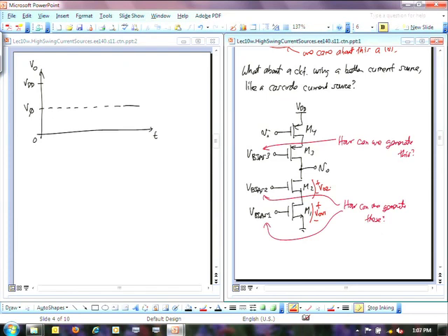And so because of that, I could say that V out min for this device is going to be 2 times an overdrive voltage. Right? And that would be the maximum swing that I can get out of this circuit here. That's what I want. Okay, so if I had to plot that maximum swing, then from the bottom, I might have 2 times an overdrive voltage. And from the top, now I've got 2 PMOS devices looking up that way. I've got to drop across this. The smallest voltage I could drop across that is going to be another 2 V overdrive voltages.